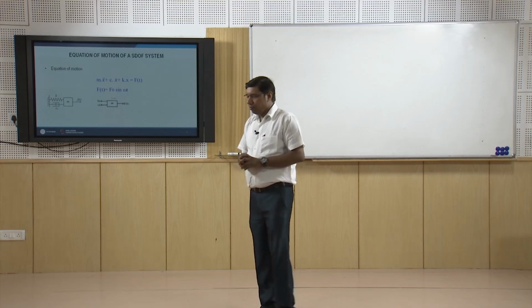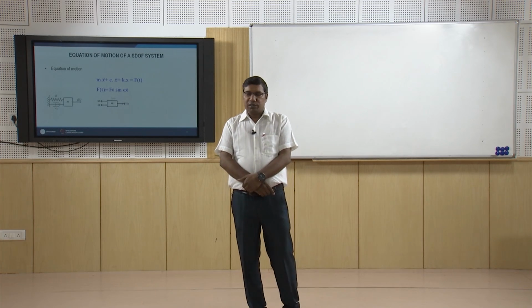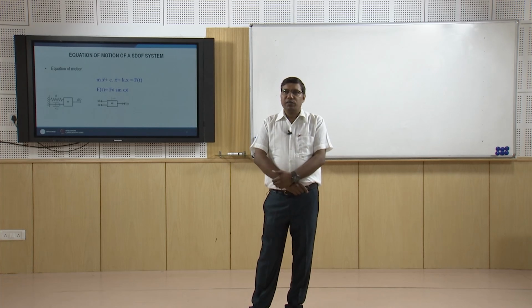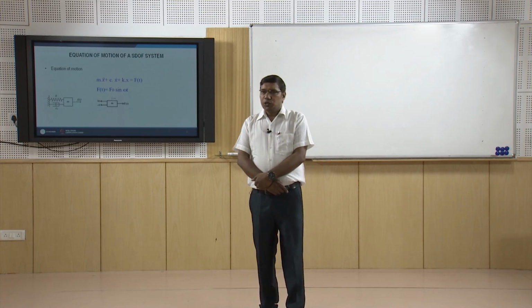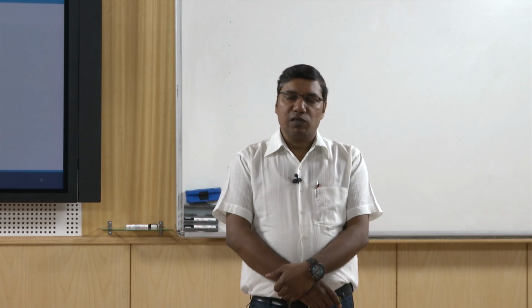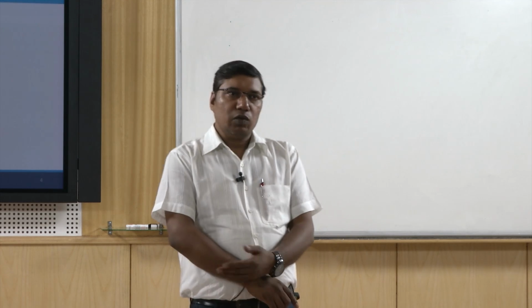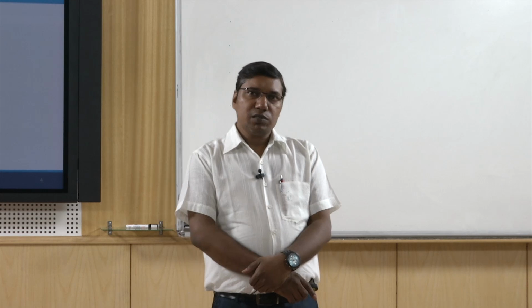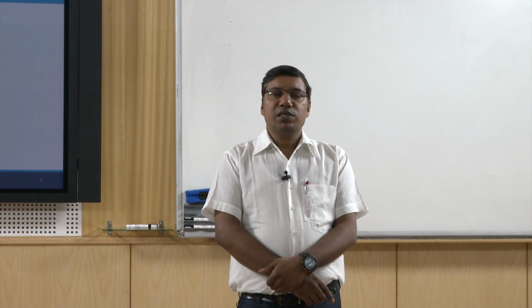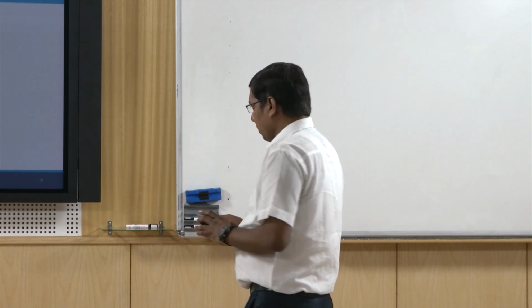So we will follow a similar analysis procedure to what we discussed in the previous lectures. We have a system, we isolate the system, make a free body diagram, show all the internal and external forces and inertia forces, and we apply Newton's law of motion or D'Alembert's principle, and we find the differential equation representing the equation of motion of that system. Then we go for the solution of this system, and the solution will give us the response of the system, and based on the response we can get some insight into the characteristics of the system. So we follow the same procedure.